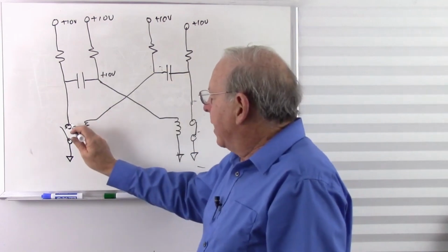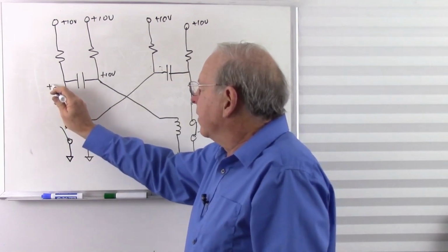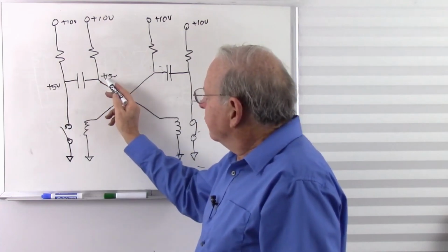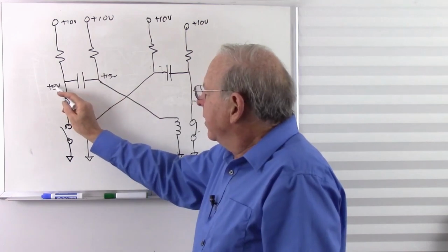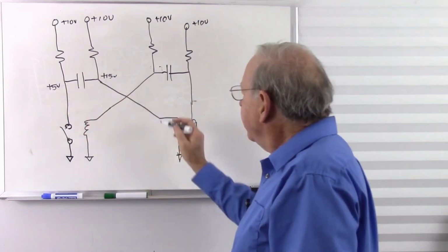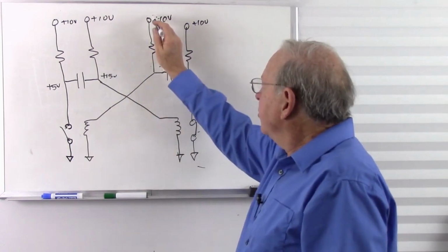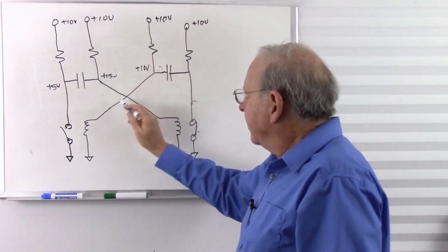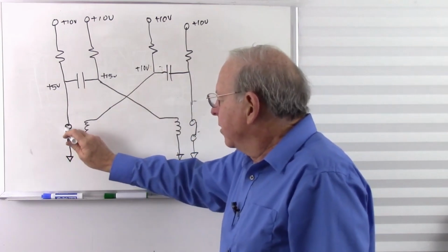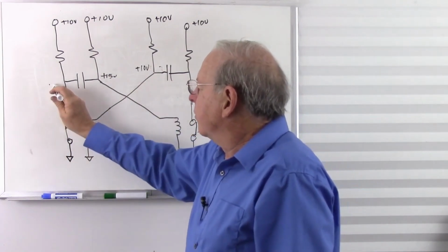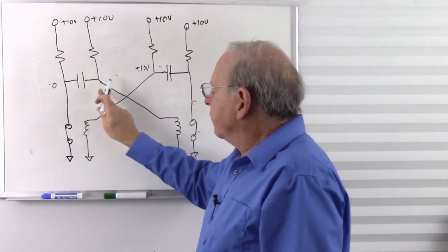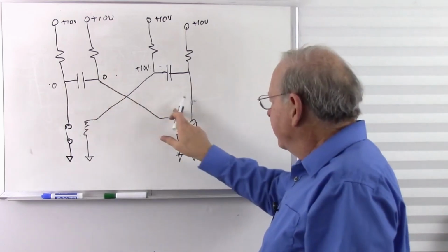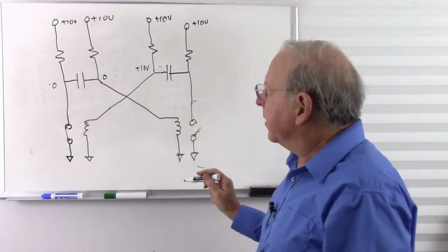And when this relay opened, what happened? This jumped up to plus 5 volts. That jumped up to plus 15 volts. This voltage slowly drops down towards 10. This voltage slowly climbs up towards 10. At the same time, this is now charging. Current's flowing this direction. When this reaches 10 volts, that energizes this relay, closes that. What's that do? It pulls this voltage down to 0. There's no difference in the two voltages. They were both 10 volts, and this was pulled down to 0. That puts 0 volts here and pops open that.